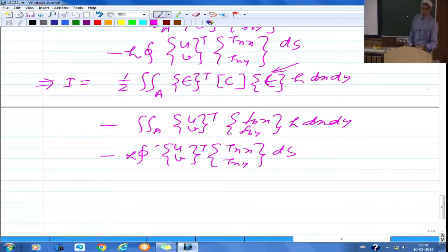A more rigorous way of looking at that is, of course, through the differential equations, and then getting the weak form and arriving at primary and secondary variables. But in this case, we can also identify by looking at our energy functional that the highest order derivatives are of u and v. In this case it is straightforward. The highest order derivative of u and v is the first derivative, so one less than that means you have only the variables themselves, u and v, as the primary variables.